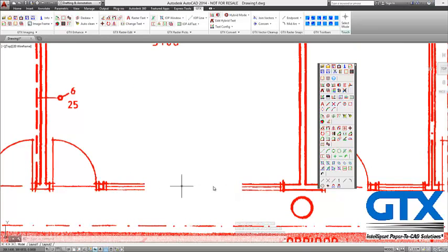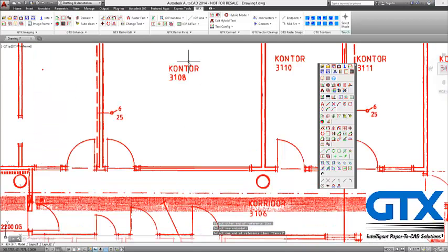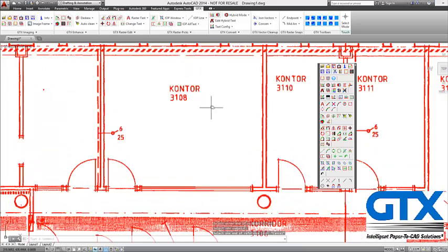I can also repair the broken lines in the drawing, so I can use this command called change line. And what I do is I say, right, I'm going to pick a line from here to here and I want to stretch it across to here. It takes the average thickness of the line and then stretches it across. So I want to use that line and bring it across to there, and that line across to there. So now I've repaired my three lines for the external wall.